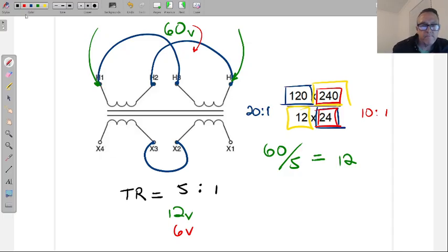There's this thing that happens when you run wires over a very long distance. It's called voltage drop. The further away you are from the panel to the load, like if you're running 1,000 feet of conduit and wire, that's going to have a lot of drop in voltage. So you might start off with 240, but by the time you're measuring the voltage 1,000 feet away, you're going to have much less.